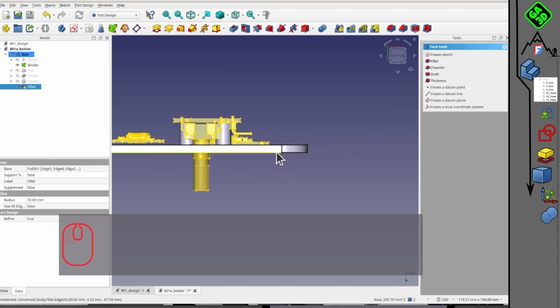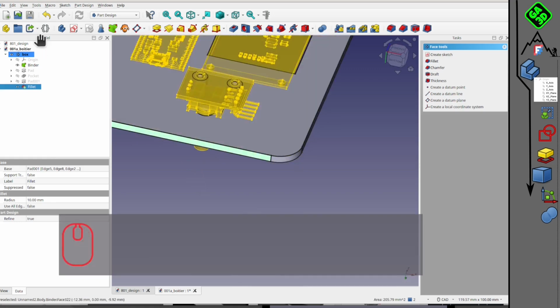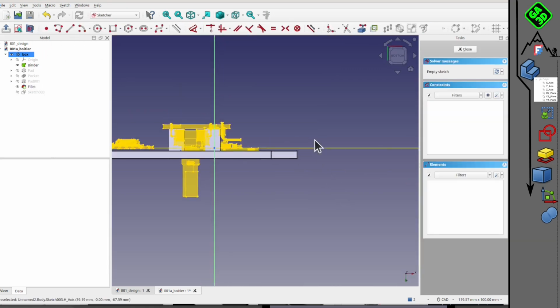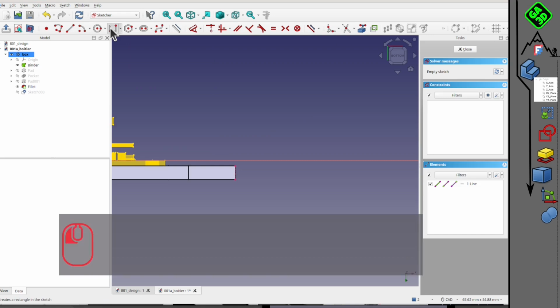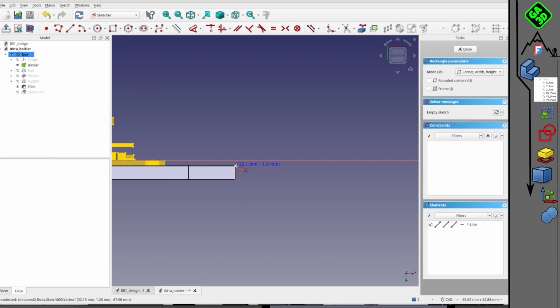So now we have our FreeCAD 1.0 new feature that allows you to enter dimensions directly, which is very useful. The way we want it to be a little solid, so 3 mm thick. And then we're going to do the case with 25 mm in height here. So it starts there where we've got the beam.